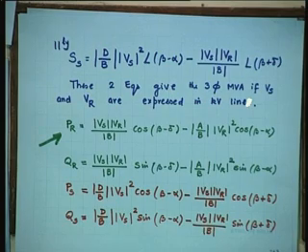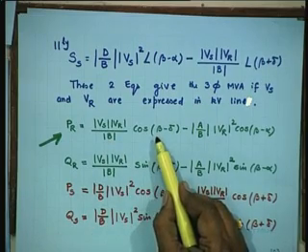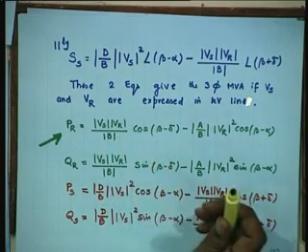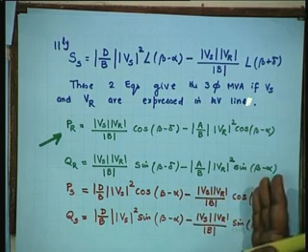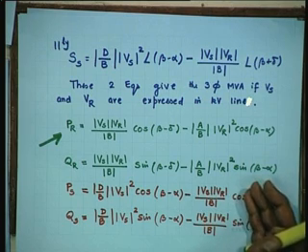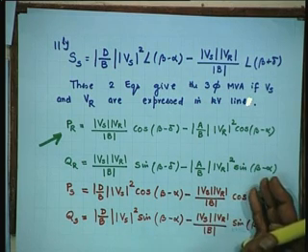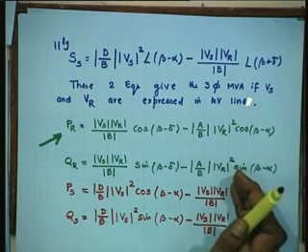By maximizing, or very simply, the first order derivative with respect to the control variable should be 0. So, what is the control variable here? A, B, beta are all fixed, once the line is already let. Vs, Vr normally we fix at 1 per unit, so they are not variable. Then what is the variable here? Delta. Delta is the only one you can change, the rest of them are fixed more or less. So, delta is the only variable.